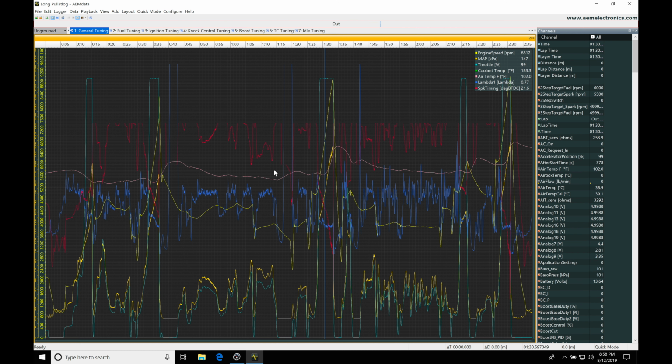So this data log right here is going to represent about a 2-minute and 35-second drive cycle, and we're going to find that we have several areas that we're at full throttle. So we can see, looking in our cursor key here, in the light blue color, we're going to have throttle position. If I click on it, we can see that it's going to highlight in the actual plot here where we have our blue trace. That's going to be found here.